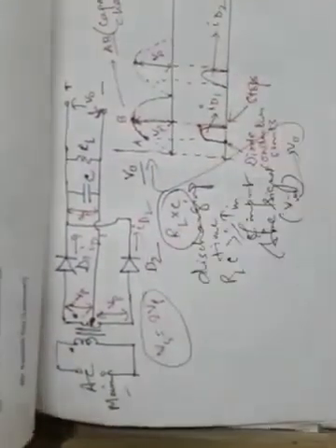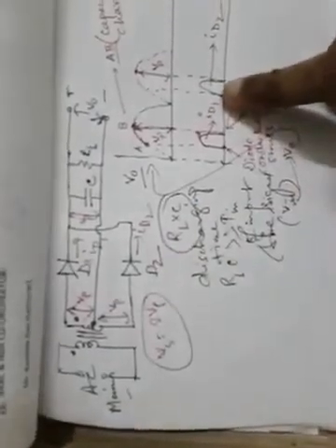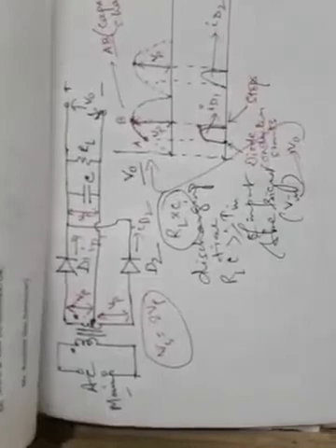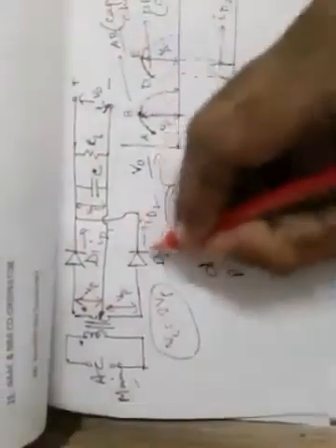So in the second half cycle of the input signal, D2 will conduct, and once again we will get this ID2 diode current, and as a result, during this portion of the output voltage, suppose denoted by D and E, where this peak point is E, during DE once again the capacitor will charge because of the conduction by the diode D2.